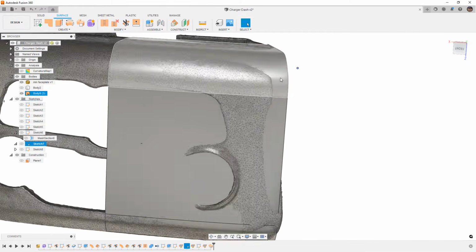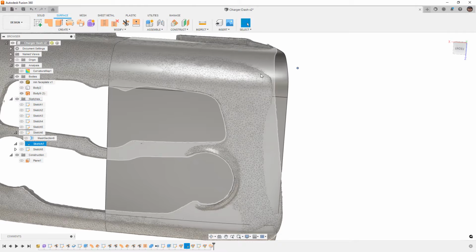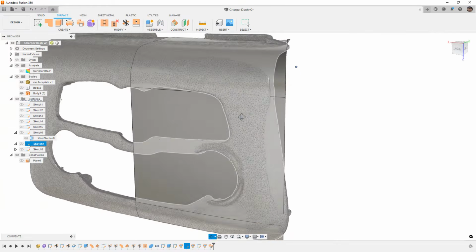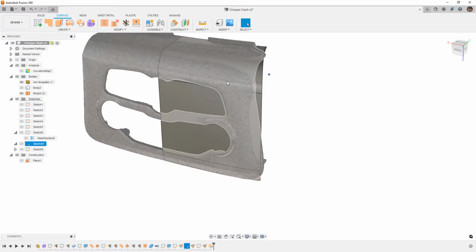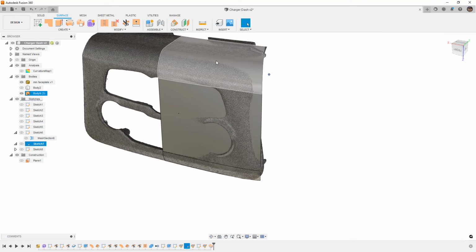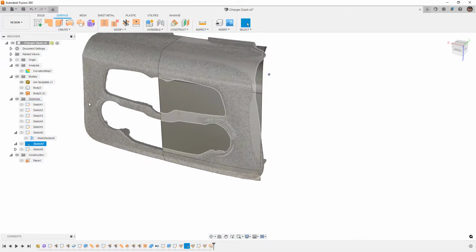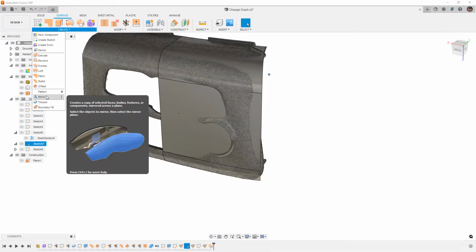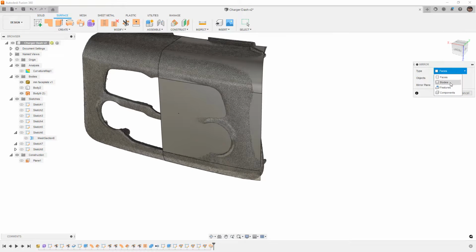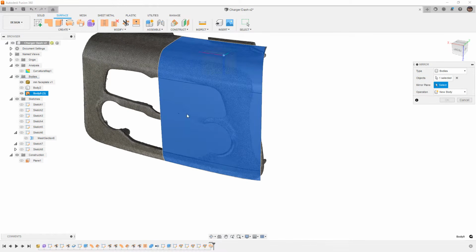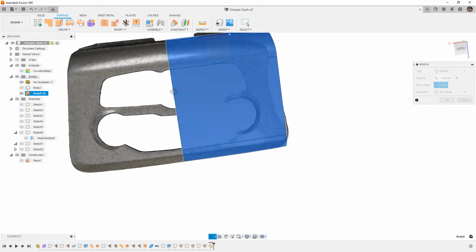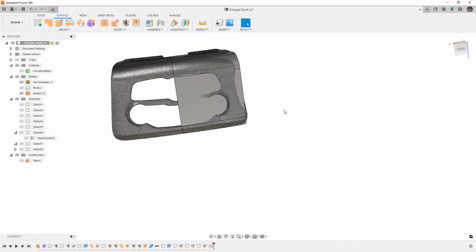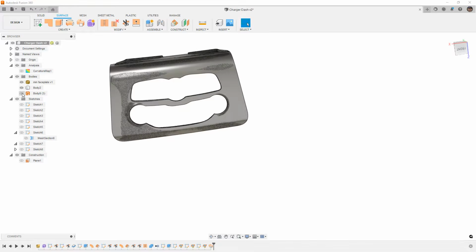You can see that with this method, it's a little bit trickier to get that underlying shape to match unless we really spend some time and figure out where the best places for those mesh curves are. Probably a good idea to put a mesh curve here instead of one up top. We could do this in multiple surfaces, but ultimately what you end up with is you take this, let's go ahead and do body. Take that body, you mirror it. We don't have a mirror plane, so we would need to create one. But then we would just simply build it like we did the other version, the solid body version.